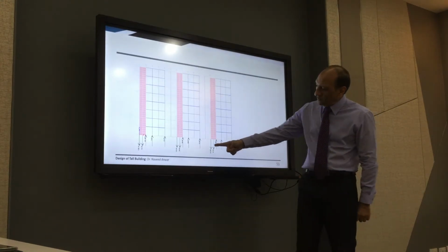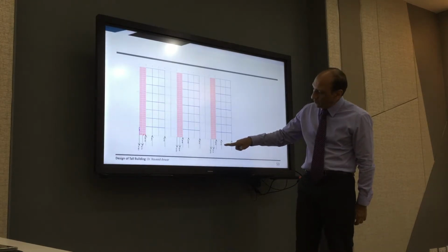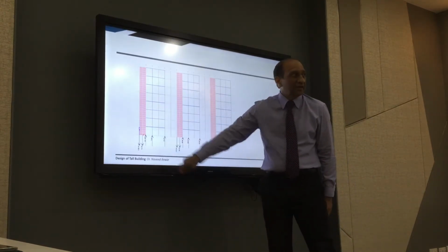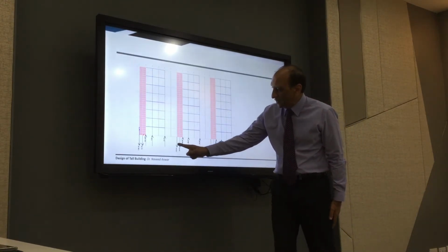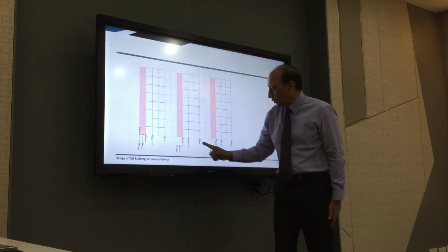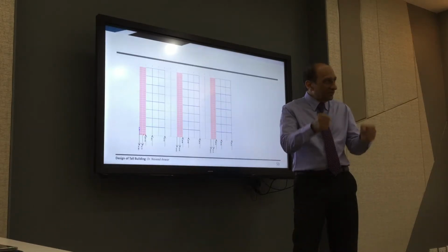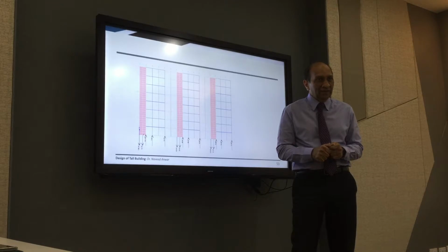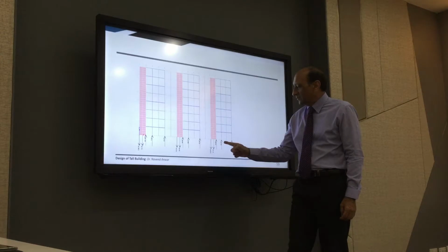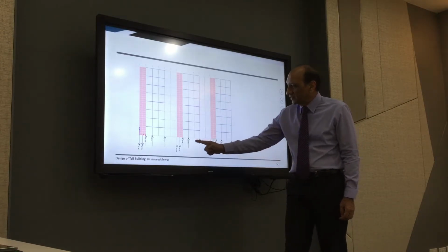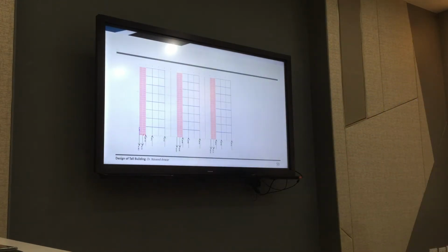So you can see also from the numbers, the axial force in this column is 53, 36, and only 7 kips or kilonewton. And you can also see the axial reaction here. So here 129, 93, and 76. That means the bending moment in the wall is reducing. Tension compression in the local bending moment in the wall is reducing, but that bending moment is now shifting to the next column. So by studying these supports and forces and shear in the frame, you can understand a lot